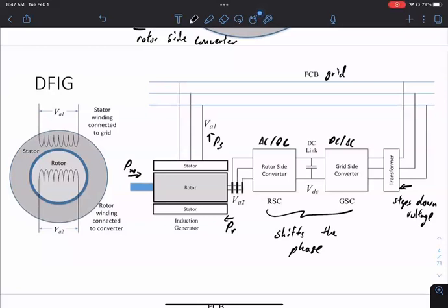Yeah, you have to line up the frequency, but that's pretty easy to do. Because you have a measurement here, you can measure the frequency of the grid. So you know exactly what the frequency here is. So you can have a pretty simple feedback controller tracking this frequency. Basically, you have a phase lock loop, and you lock onto the frequency here. The frequency doesn't change all that much on this grid, so the frequency change is sort of slow. And your power electronics is normally much faster than this frequency change. So it's an easy frequency to measure.